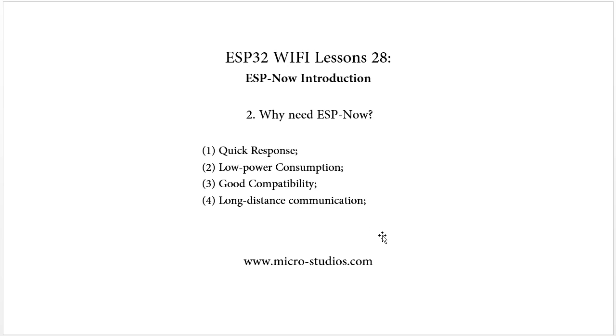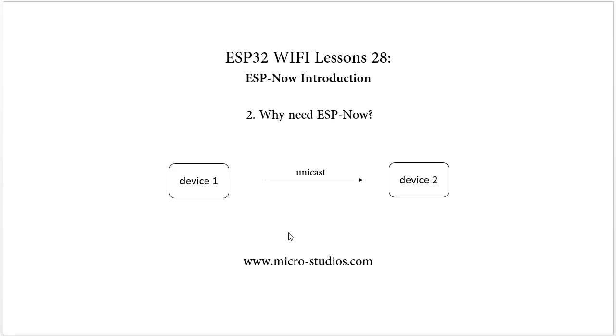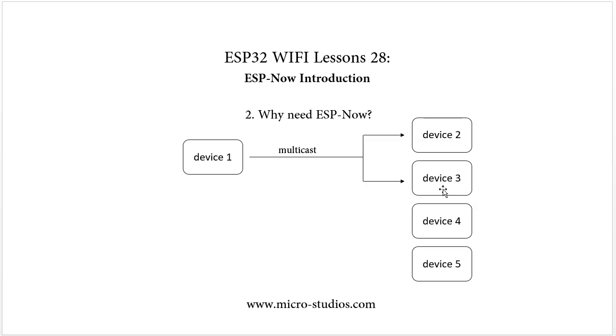Okay, so next, the ESP-Now supports unicast, multicast, and broadcast. So what's the unicast? The unicast is like this: one device sends data to another device, 1-to-1. The multicast is like this.